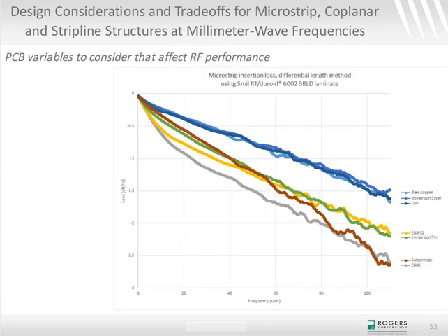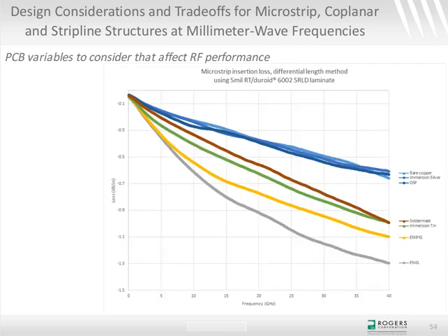Here is an output of one of the studies I did years ago. Unfortunately, at the time, I had not figured out signal lengths very well at millimeter wave range, so beyond about 42 or 44 gigahertz, the return loss is not too good. So this is kind of a good general thing to look at for trends. But if you truncate this down in the range of frequencies where it was well-behaved for return loss, then 10 megahertz to 40 gigahertz, you can see pretty clear differences here.